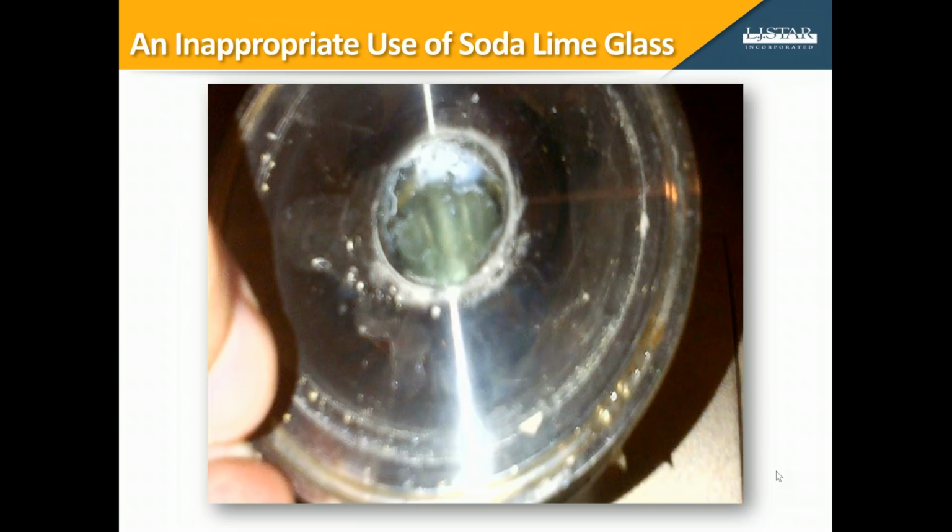Here's an example of a bad sight glass choice. An independent inspector for an injectable drug maker mistakenly recommended installing more powerful lights for inspection vessels for cleanliness. In fact, the light ports were made of soda lime glass that had etched so badly that light could not shine through them. The one shown here also shed a glass shard into the process vessel. Another concern from a safety and product contamination standpoint.